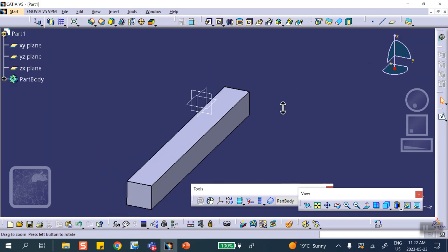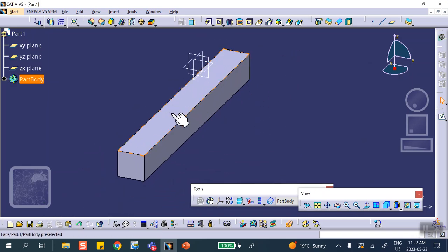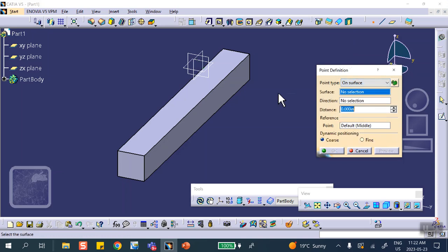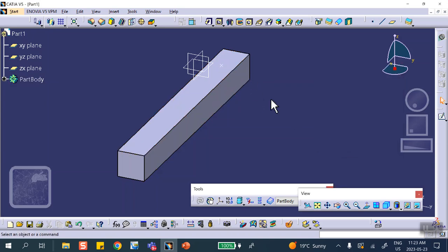There we are. Now, I'm going to create a patch here where I want to apply a pressure, for example. And I want to create a point there where I want to put a concentrated force. Let's start with a point, for example with a coordinate on this surface. There's the blue one. See the blue dot? It's going to create a point there. You can see that right there. It's on that surface.